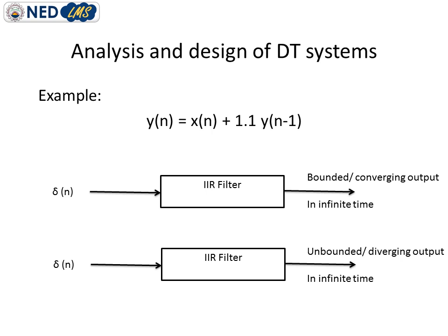So we are more interested in the first case, which is the stable case of an IIR system. And why are we not preferring an FIR system? Although an FIR system always produces stable output, FIR systems are very complicated to design. And another thing, FIR systems have a large number of computations involved with them. So the number of computations also increases in FIR filters, and the design of FIR filters is also very complicated.